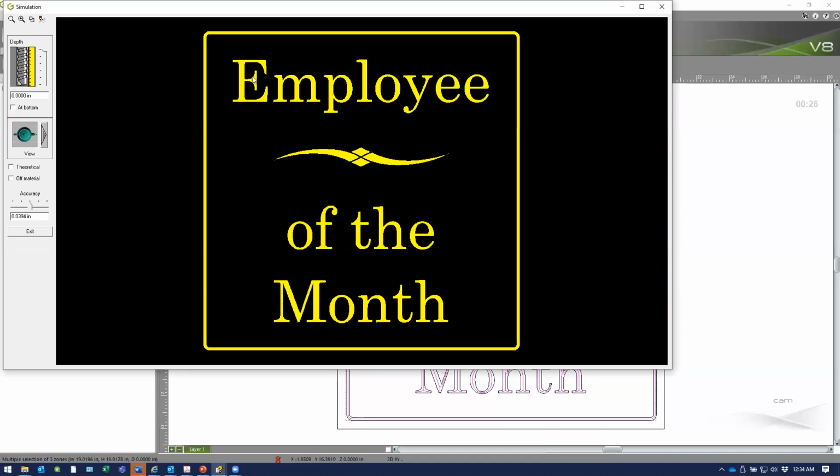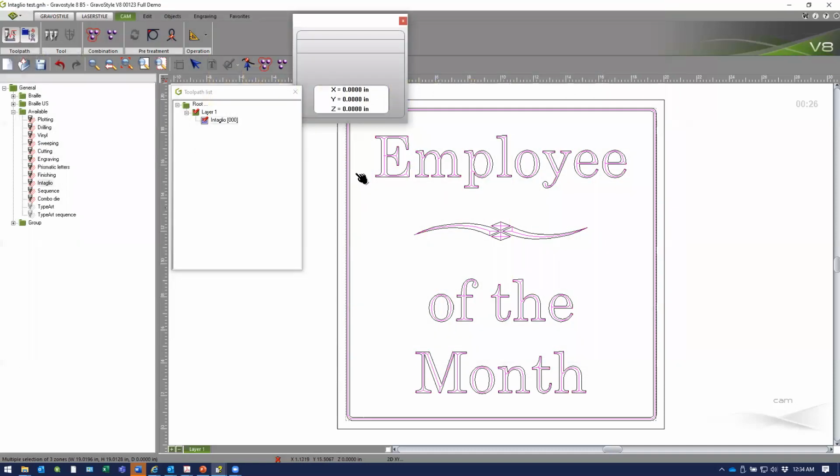If in this view, my tool paths don't appear to be clean, then it is not going to render and give me a clean image. So for instance, if these cross lines were washed out in this image, they're likely going to be that way on my finished product. So go back and revisit your tool paths, make changes to the depths, make sure you have the right angles set for your cutter in the tool library before you proceed and waste material, essentially.